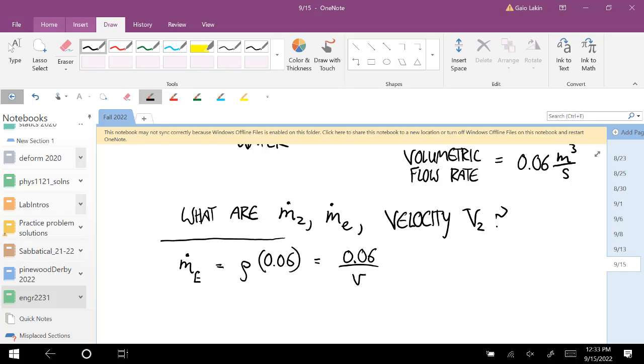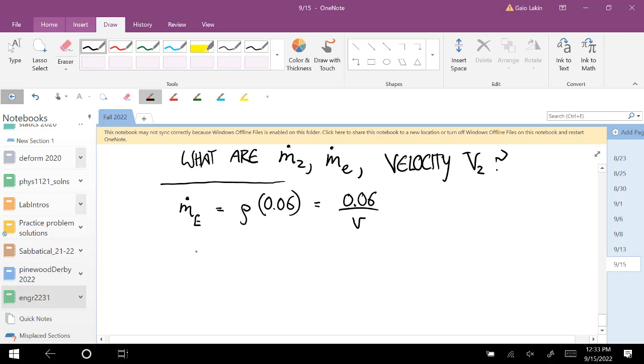But since we have that pressure, we can look it up. It's a pretty high pressure, which means the saturation temperature is pretty high, which means that specific volume is going to be at least a bit higher than 1 times 10 to the minus third. So look in the pressure saturation table for liquid water.